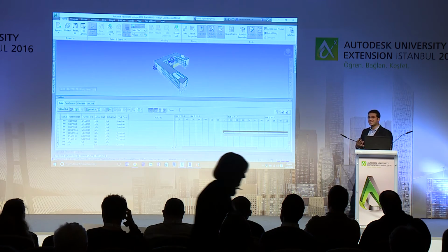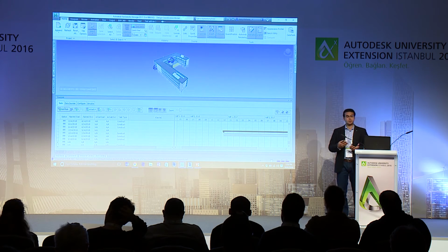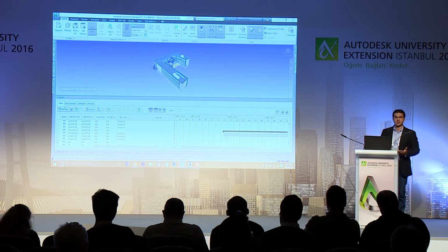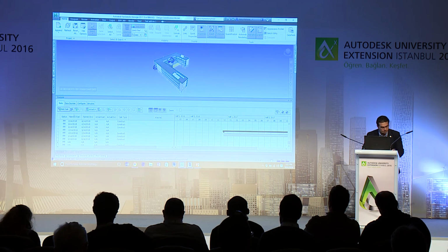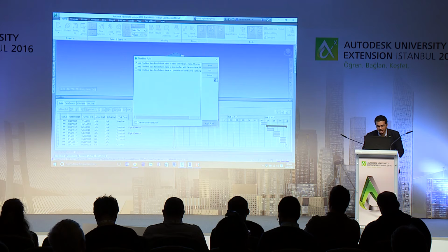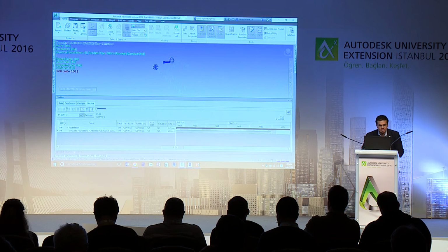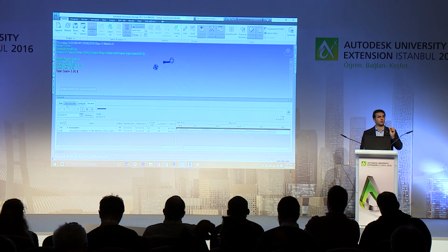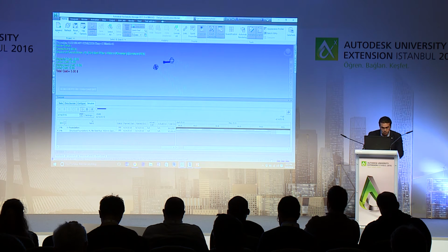So they can easily communicate the plan, they can easily communicate what is going to happen in the project, and later on they can produce plan versus actual reports. Linking is very easy. I can actually apply a rule to link my model element to my project and simply go to simulate and then start what we call a 4D simulation, which is the 3D BIM model plus the time plus the cost associated with each task coming from Primavera or MS Project or whatever planning tool you are using here.